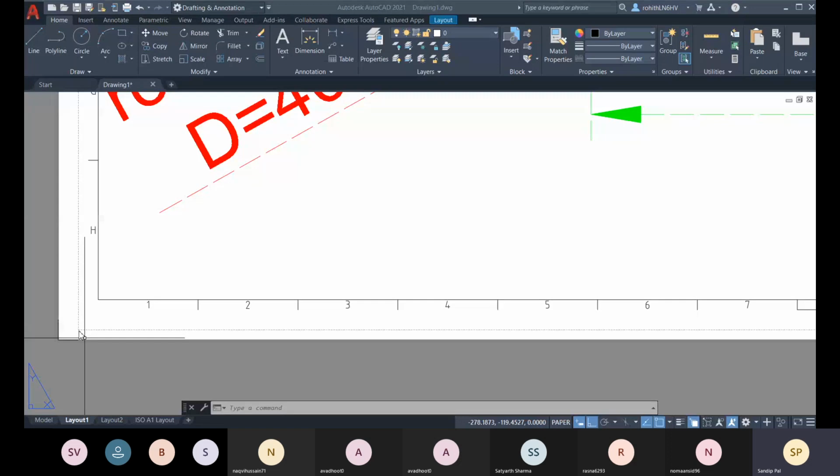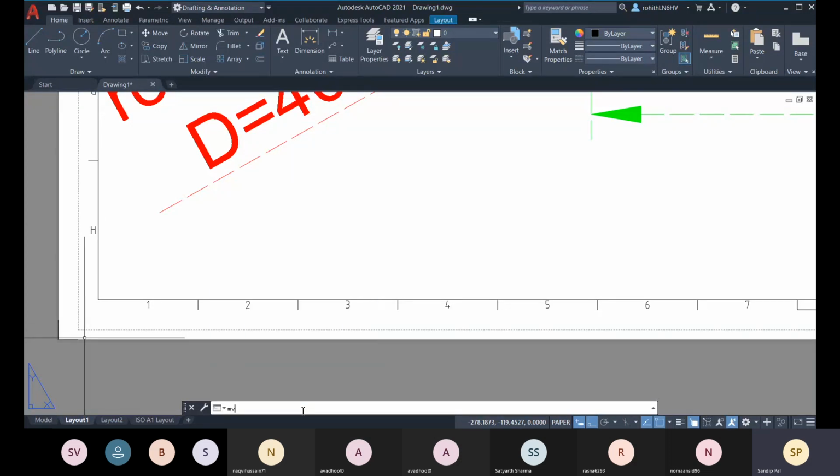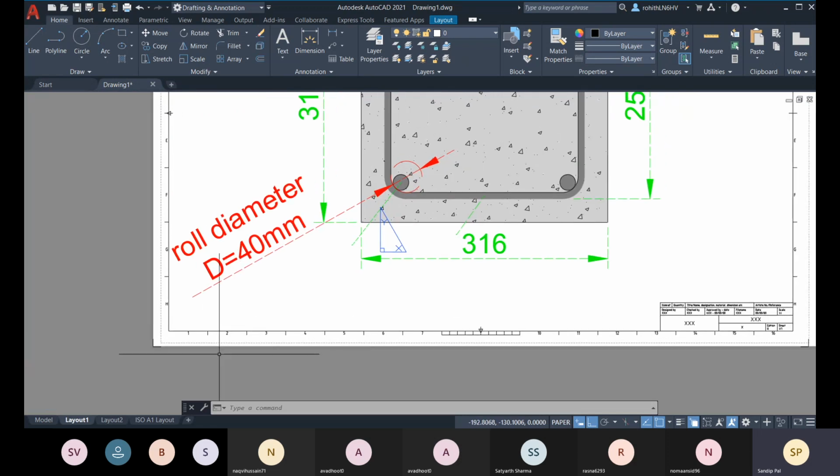I just need one point there, right? So there is nothing wrong with placing a viewport over there. With the viewport, with MVIEW or viewports, you can place the viewport so that you can get the point over there, and you can identify the coordinate value for placing your title block. That's a simple thing.